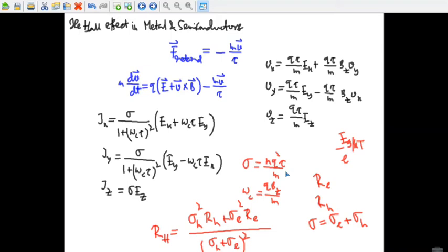So in a semiconductor, the band gap is relatively small and electrons may be excited by thermal energy to jump the gap. This process allows an electron-like state near the bottom of an upper band and a hole-like state near the top of a lower band to come into existence.